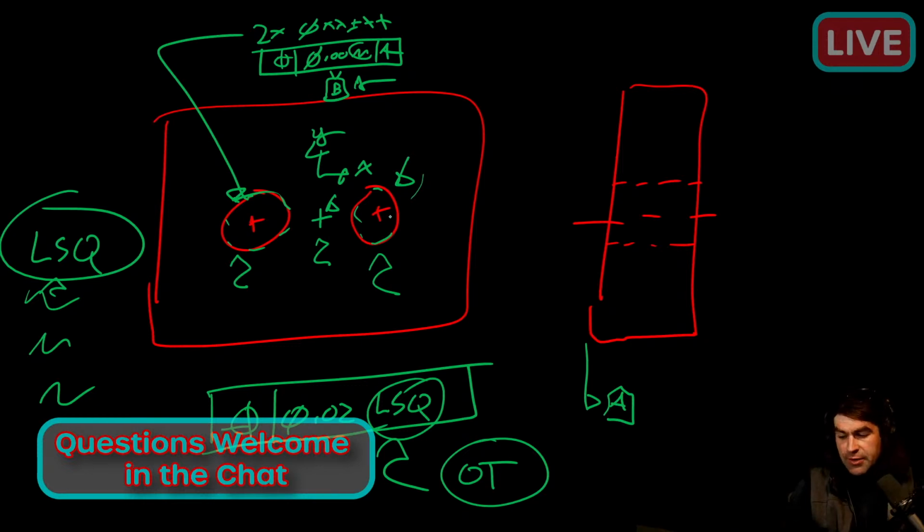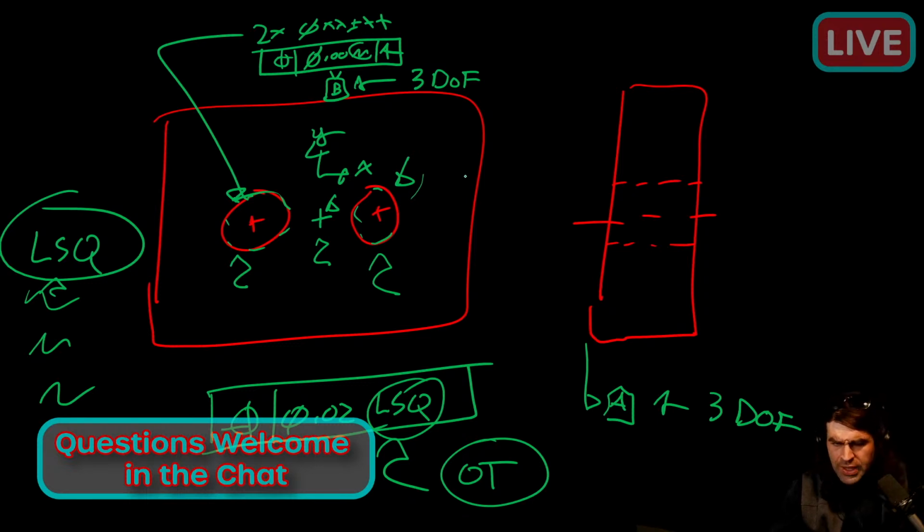Okay, so yeah, we're saying the two holes control 3 degrees of freedom. I'd agree with that. So this datum A takes away 3 degrees of freedom, and these two holes take away 3 degrees of freedom. So yeah, that would be all 6. It's just a matter of getting Calypso to pick up what you're putting down. But it's also important to recognize in this situation, practically, does it make a huge difference? But this means something different than